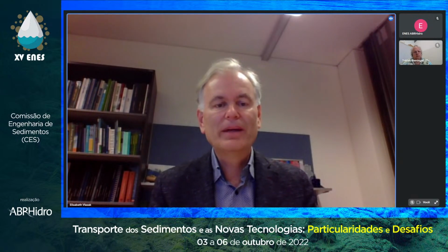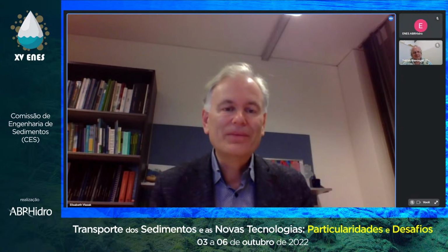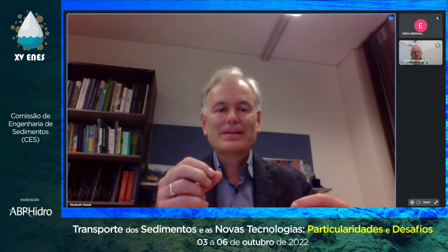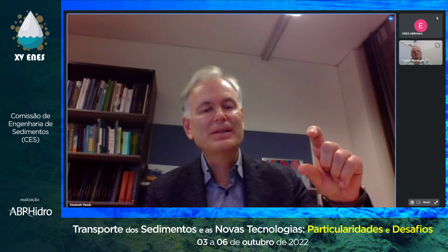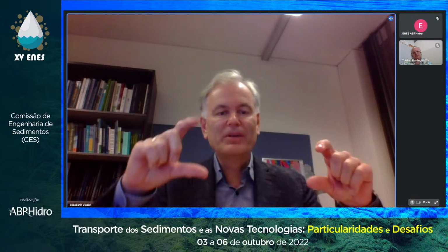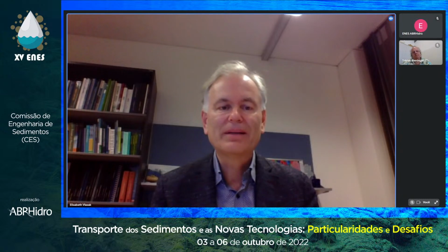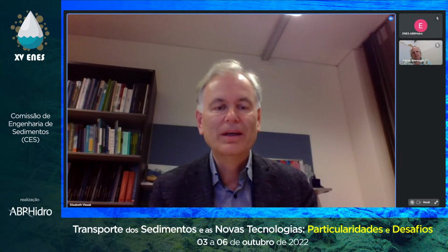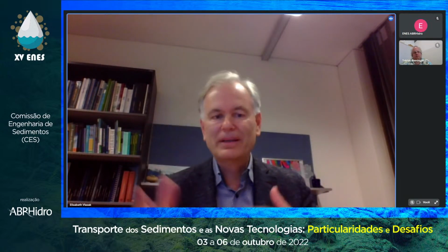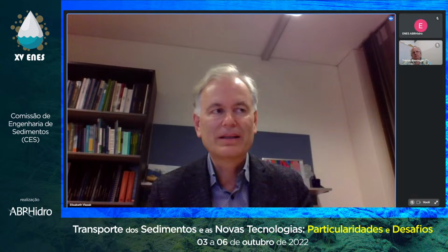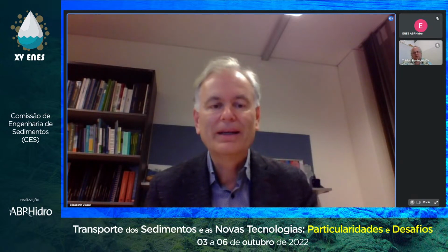I agree with you. We have generally to look into this, because the biofilm itself then hinders the capacity for flushing, because the critical shear stress, if you compare no biofilm with biofilm, it might be 3 times higher. So you would need 20 newtons per square meter, suddenly you lose, 60 or 100 you would need. So the biofilm is quite a complex structure, as we all know, with bacteria in combination with other structures that get there, as one indicator.